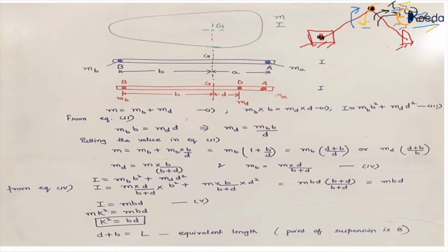There is some torque, some omega, some angular acceleration in the crank, which is enough to resist the inertia torque in the system. But if you increase the mass, the inertia force increases. Now you have to give some extra torque to the system to ensure that the motion does not get affected. So in the further video, we'll discuss how we can create a dynamically equivalent system in such a way that we can provide this extra torque to the system so that the effect of inertia torque can be minimized. And this torque is also called the correction torque, right?